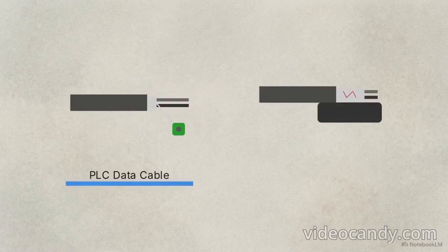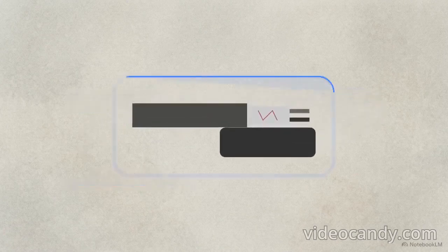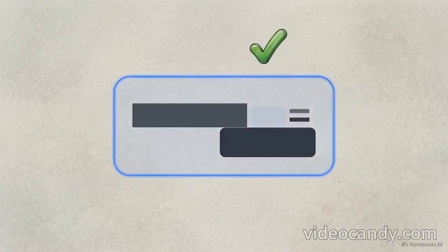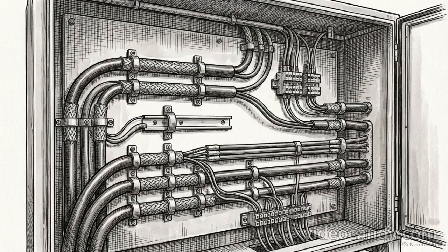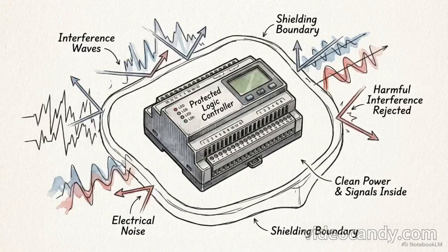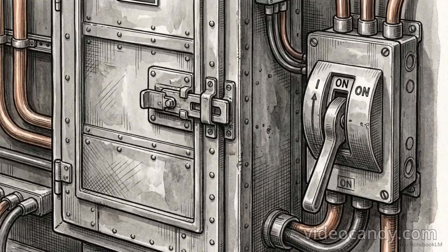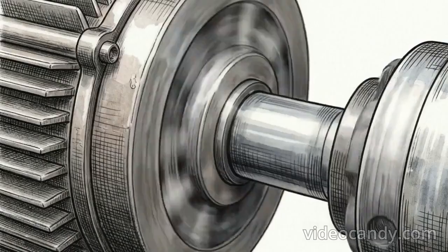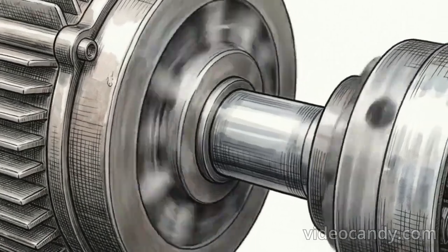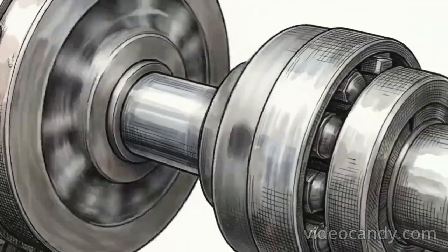This shows why it matters. On the left, a twisted pigtail acts like an antenna, radiating high-frequency noise into nearby data cables. On the right, the exposed shield is secured with a 360-degree conductive clamp to an unpainted grounding plate, creating a continuous Faraday cage. Maintaining electrical hygiene and grounding discipline contains switching noise at the source. This prevents intermittent signals from disrupting the logic of your control system.